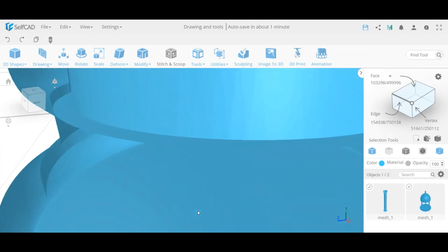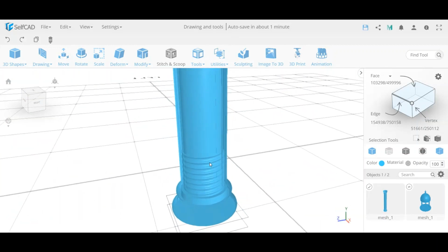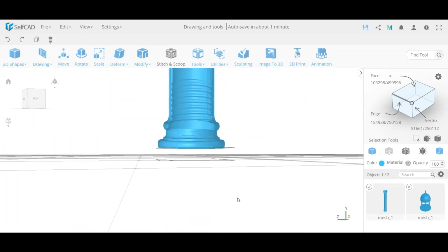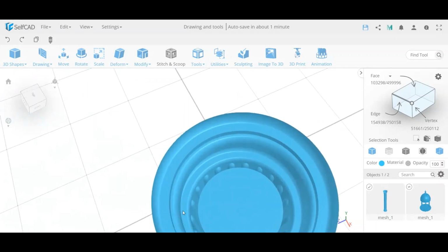So if you're going to 3D print this, that's probably the idea. You can print them separately because otherwise you need a tremendous amount of support structure between these things, and it's just a waste of time and money and it'll make it more difficult. But if you print them separately, the top of it, separately the bottom, and then separately the pillars, and screw them on, this will make it look really nice. So it looks like there's been some screw setting over here, and I can't unfortunately see, and over here looks like it was just a place to put it in.